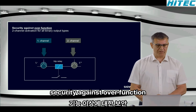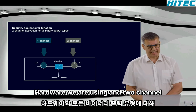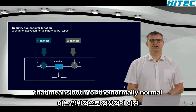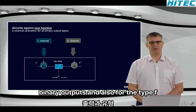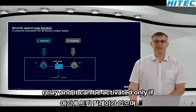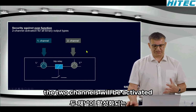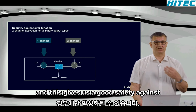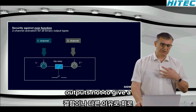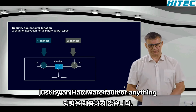Security against overfunction. In general, in our SIPROTEC 5 hardware, we are using a 2-channel activation for all binary output types. That means both for the normal binary outputs and also for the type F binary outputs. So we have here the trip relay, and it can be activated only if the 2 channels are activated. And this gives us good safety against an overfunction of our binary outputs, not to give a trip command to a circuit breaker just by a hardware fault or anything else.